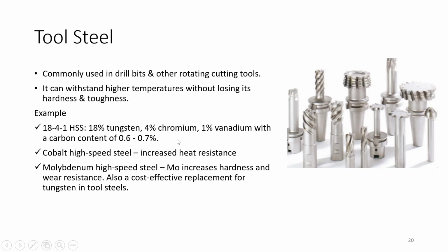That means these elements act as a substitutional defect, and they give hindrance to the slip of your material. For your material to deform, there should be dislocation movement. So if anything you are doing in your material provides a barrier to this dislocation movement, then it will provide strength to the material, right?